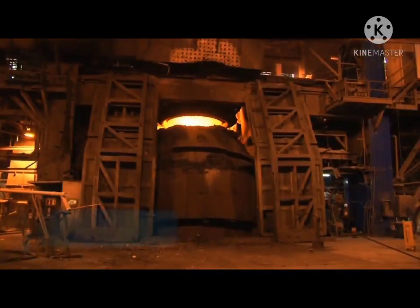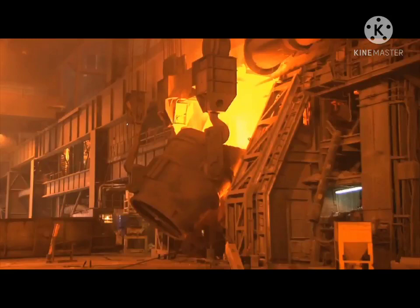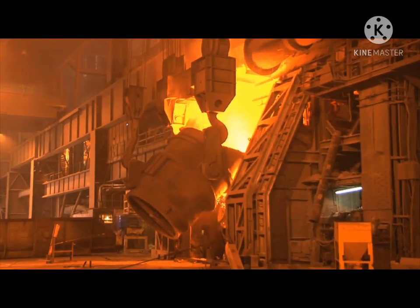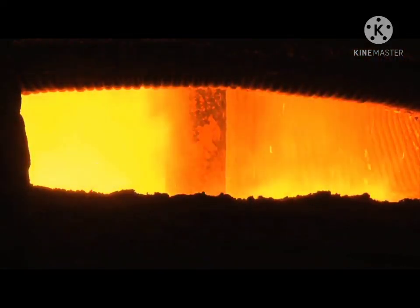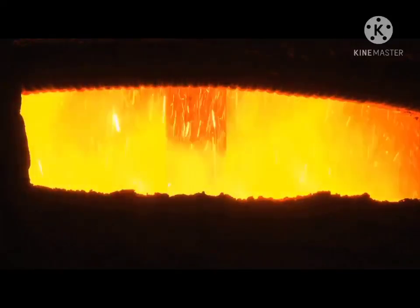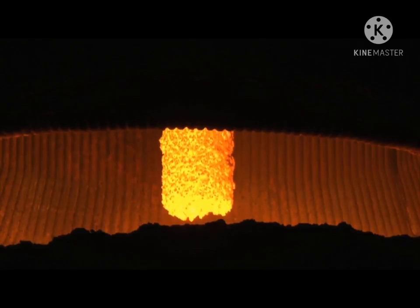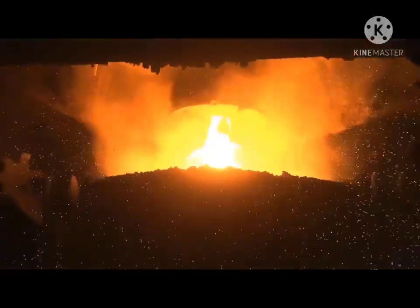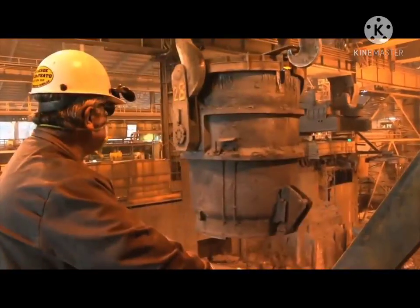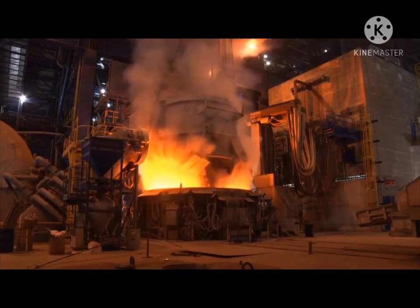Steel is a discovery of the Iron Age, a period that started around 1200 BCE. Iron ore was first mined in Central Asia and Europe. What is the Bessemer process? The Bessemer process was the first inexpensive industrial process for the mass production of steel from molten pig iron prior to the open-hearth furnace. The key principle is the removal of impurities from the iron by oxidation, by blowing air through the molten iron. The oxidation raises the temperature of the iron mass and keeps it molten.